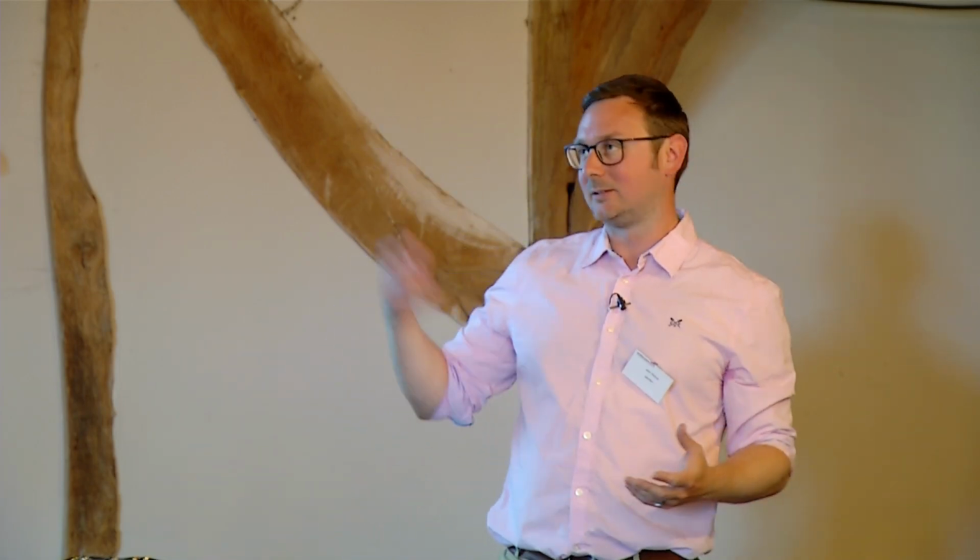Yeah, so under the previous iteration of ADB, what you had was Velux windows. Bear in mind this is previous iterations, so no longer applicable now, but the idea was that if you had a Velux window with a loft conversion, you had sufficient space, I think from memory 1200 millimetres, on the roof itself, so that people could get out of the Velux and sit on the roof and get rescued by the fire service. The reality is that each and every individual in a loft conversion or up that third storey would be able to do that is probably why it's been removed from the guidance.